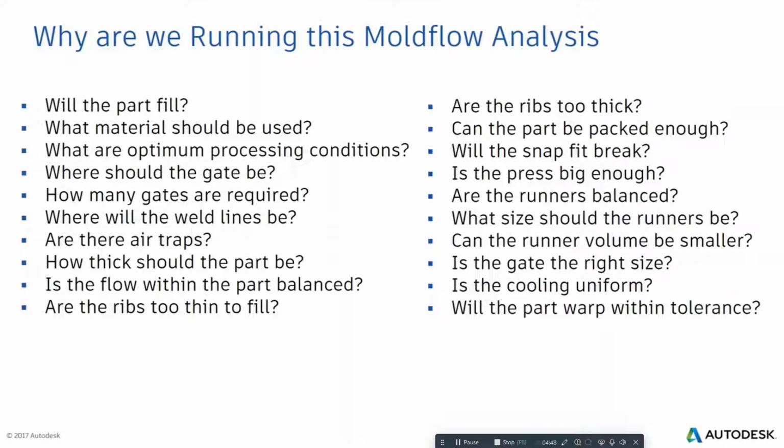Now, why are we running this Moldflow analysis? These are some of the basic research questions that you should have for each use case. All right. Firstly, you ask yourself: will the part fail? What material should be used? What are the optimum processing conditions? Where should the gate be? How many gates are required?